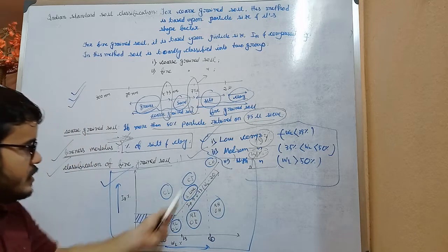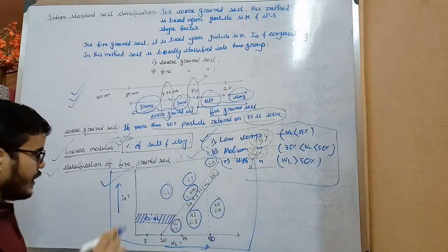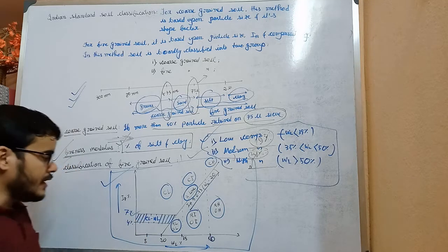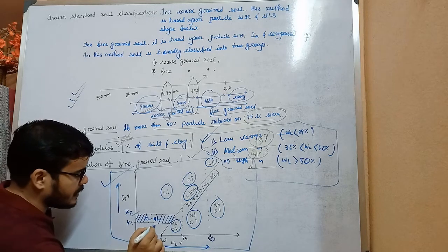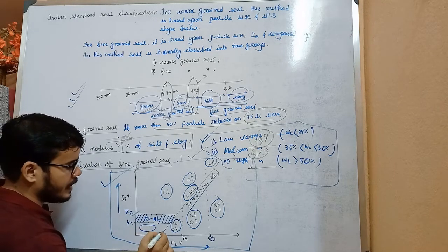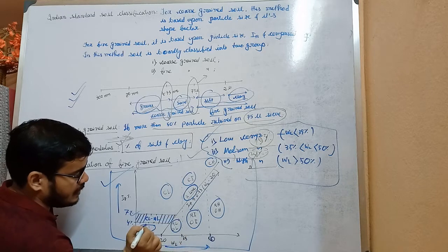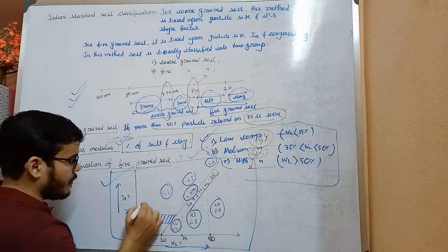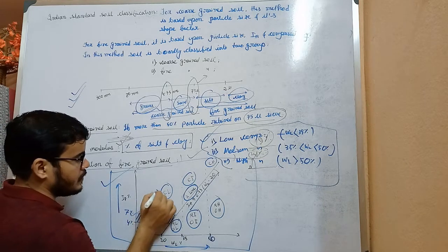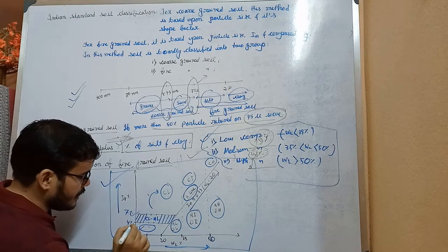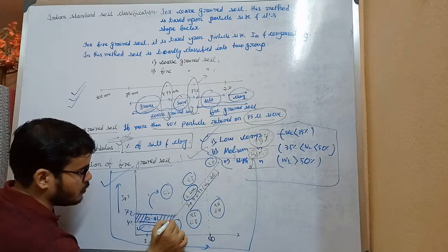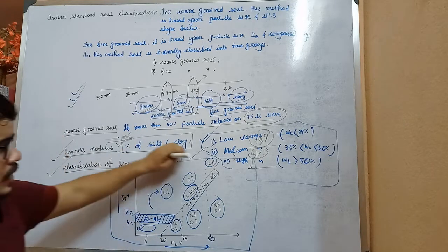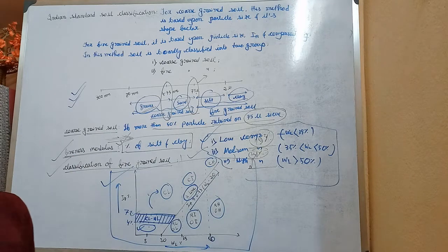Okay, and write this note very carefully. And here is a zone, that is 4% and 7%. If plasticity is below 4% and the point lies on this side of this line, then it will be also silty. Okay, if above 7%, then it will be clay. And in the intermediate zone between 4 to 7, two types of particle may be present, that is silt and clay. Draw this whole graph very carefully. Okay.